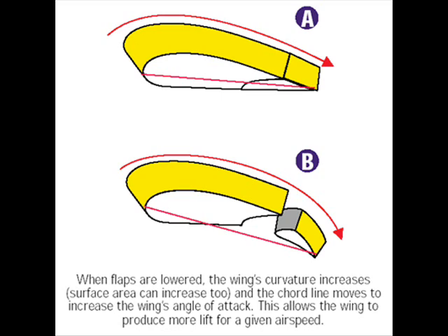What's the reason for putting flaps on small airplanes? First and foremost, they create the lift necessary to maintain flight at slower airspeeds. When landing, your goal is to approach and touch down at a reasonably slow speed. You certainly don't want to touch down at cruise speed. Such a high-speed landing may turn your tires into a few little puffs of smoke.